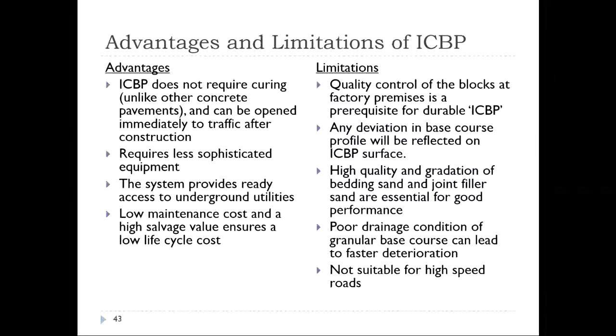Now, this requires less sophisticated equipment compared to pavers or very precise compaction equipment. You don't require these sophisticated equipments. However, this is labor intensive. And this system provides ready access to underground utilities. This is one of the major issues we face in any of our pavements, whether low volume or high volume roads. You find people coming and digging for restoring the pipe facilities or restoring the telecom or electric facilities.